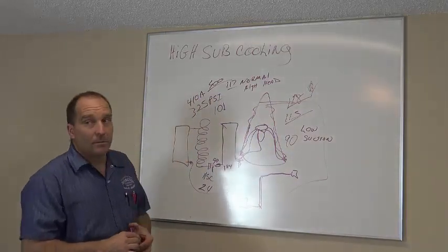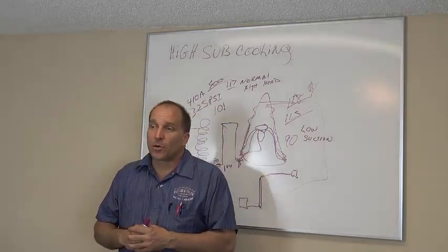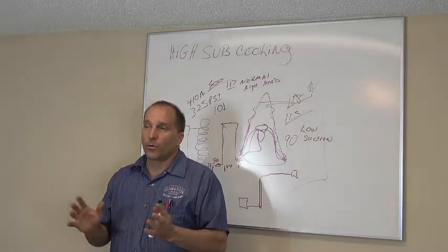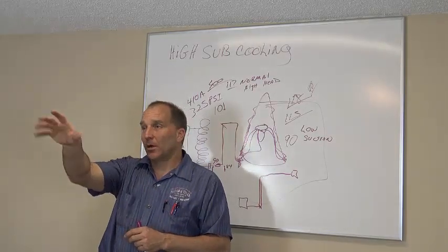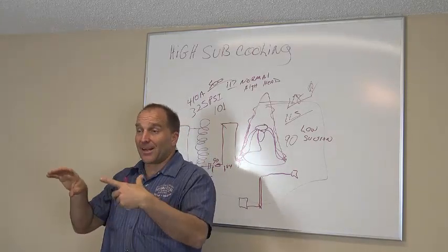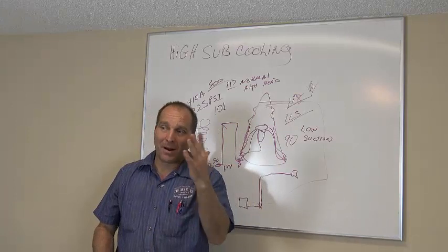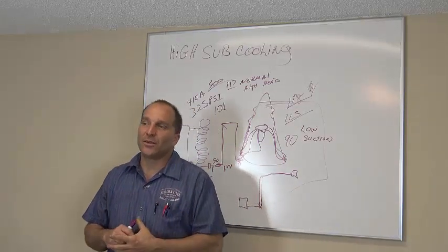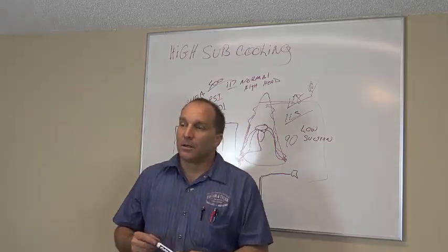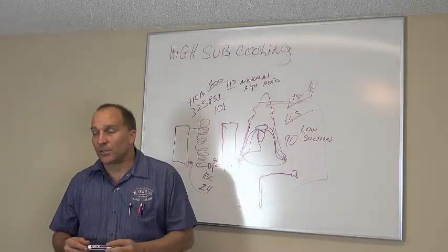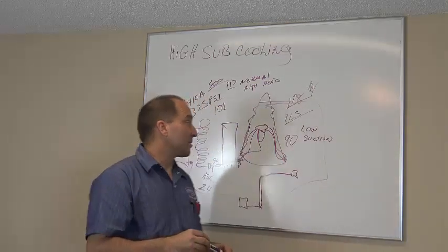How can you see the electronic TXVs? When you actually install this coil, you can take the face off of the coil, the door off of the coil, and it's mounted inside there. So what you actually want to do is unscrew it from the face of the coil, and it's got enough wiring on it, and you run it down where the tubing is, and you can run it outside the coil, and you mount it outside the coil. So now you can always get to that electronic expansion valve. Okay. What kind of units are they normally on? That's a Ruud system, Ruud and Rheem. Okay. Yeah, it's a brand new model for that system. Okay.